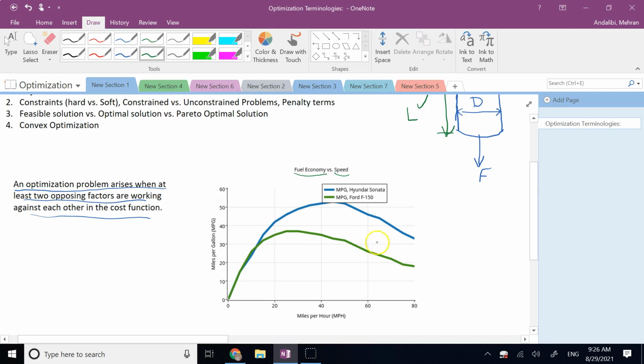The reason is there are two factors here. One is when you're driving a little bit faster, the lubrication of the machine is done better. Why? Because the oil used for lubrication, when the temperature is a little bit higher, has a lower viscosity and the friction in the machine goes down a little bit, okay? So you can have better economy because you have smaller friction.